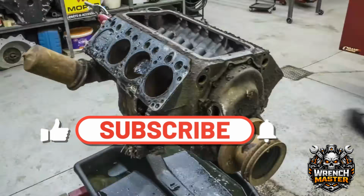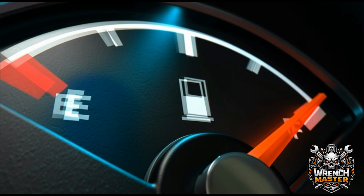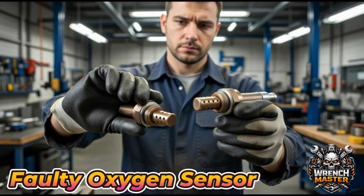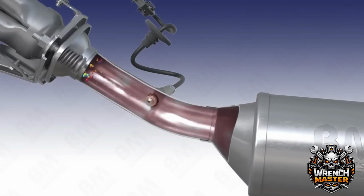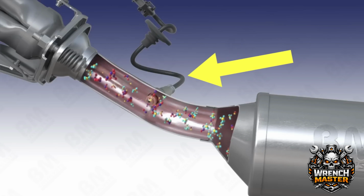Now, without further delay, let's get started. The main causes of excessive fuel consumption are faulty oxygen sensor. The oxygen sensor is responsible for monitoring whether the air-fuel mixture is correct. It does this by measuring the oxygen concentration in the exhaust gases.